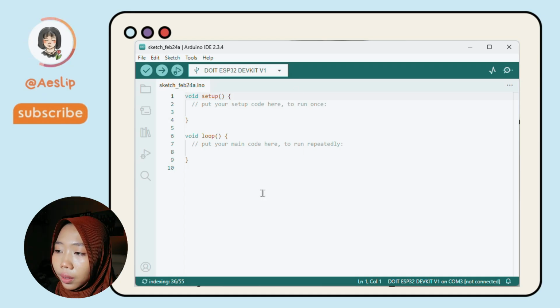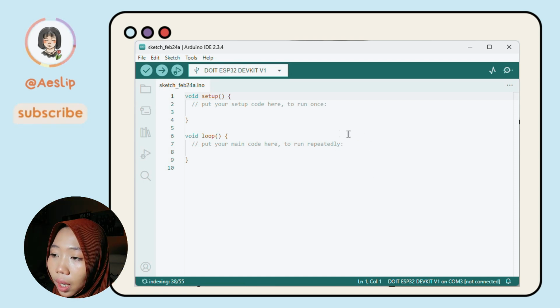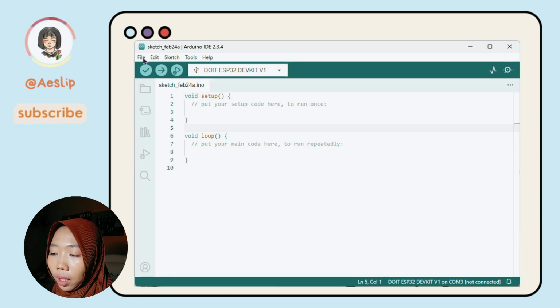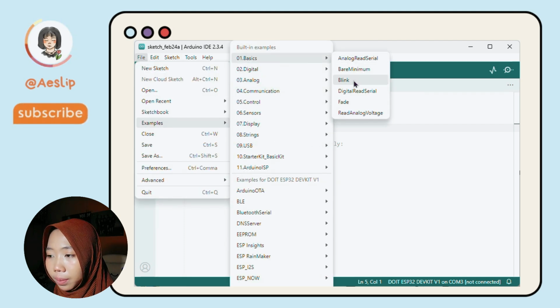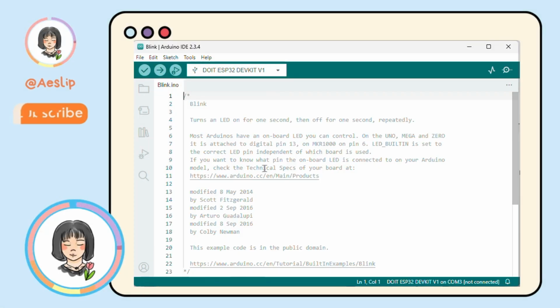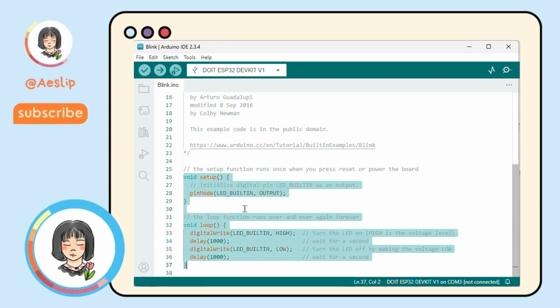Now we try our first program, the Blink LED. First, open the Arduino IDE. Move to File, Examples, Basics, and Blink. This code is written for an Arduino and designed to control the built-in LED on the board. Let's break it down line by line.